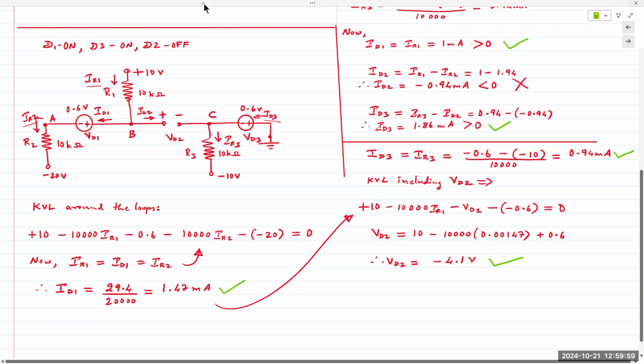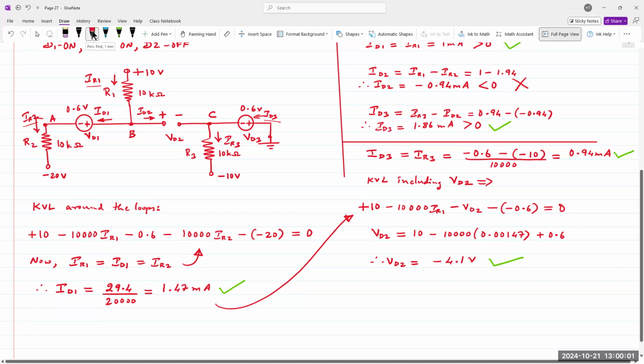And there you have it. This is the way we would analyze using the ideal diode or the constant voltage drop model. The analysis using the ideal diode model will be exactly the same, except that all diode voltages would be 0 volts. If you assume the diodes are on, there would not be 0.6; you would simply take it to be 0 volts. Everything else still remains the same: reverse bias diode, negative voltages; forward bias diode, a positive diode current.